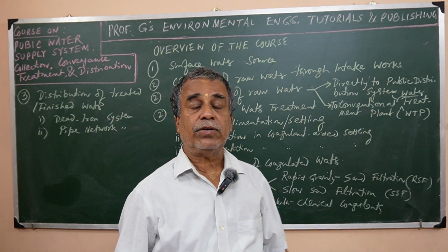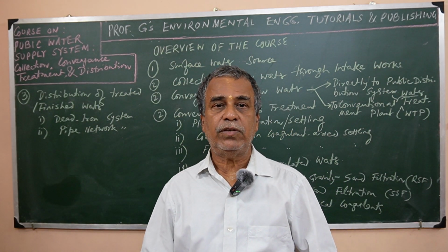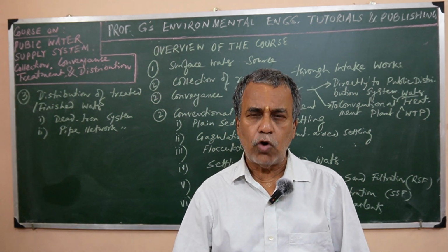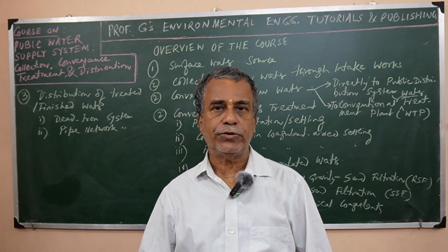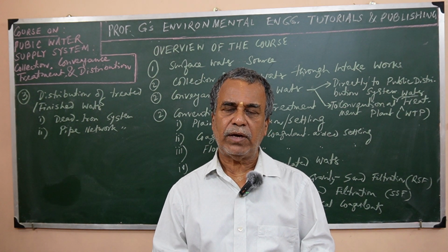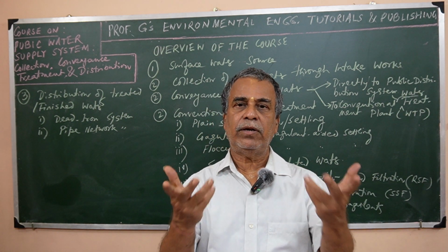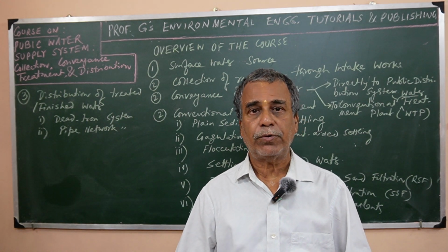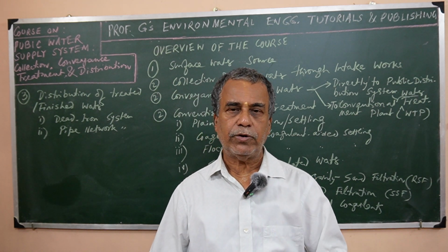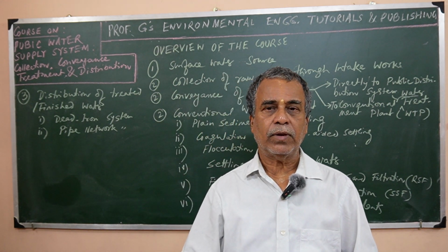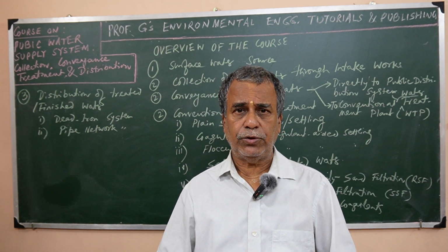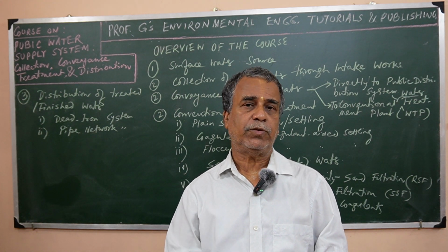For a groundwater source, the procedure is a little different, because groundwater quality is normally good and minimal treatment is required. Most of the time, only disinfection may solve the problem or complete the treatment, and then it is supplied to the public, the beneficiaries, through the public distribution system.